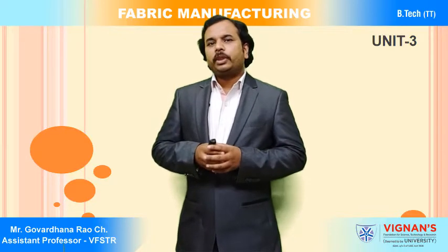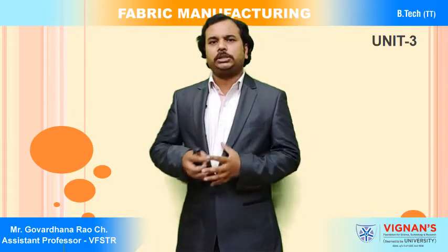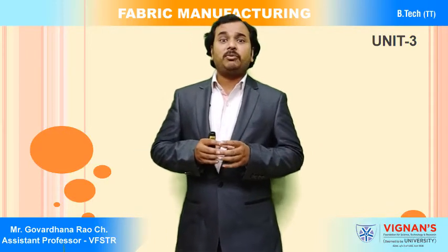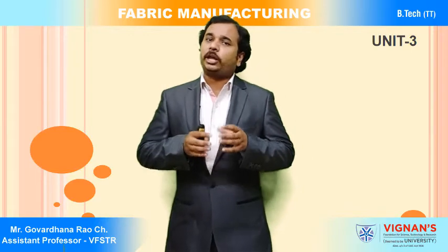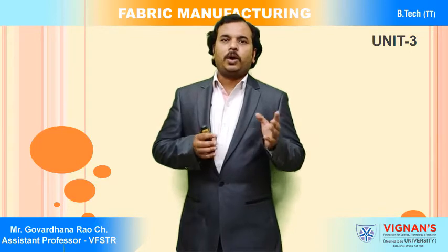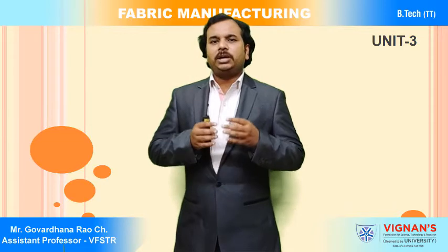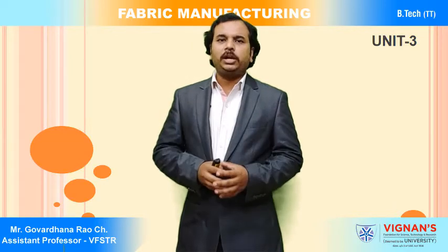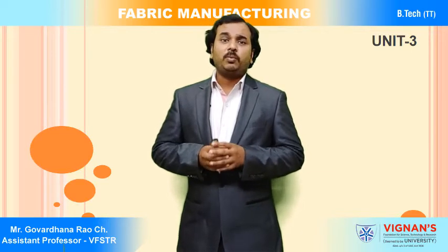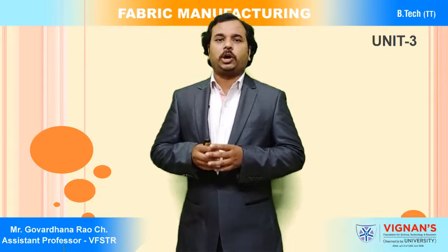Okay, for example, if we need to produce the same fabric for long runs, say 1 lakh meters of fabric, we cannot accommodate 1 lakh meters of warp in one beam, so we produce several beams in the warping machine, then sizing is done. Whenever the quality of the fabric produced in the weaving process is the same, in that case we select the knotting process in the post sizing operations.